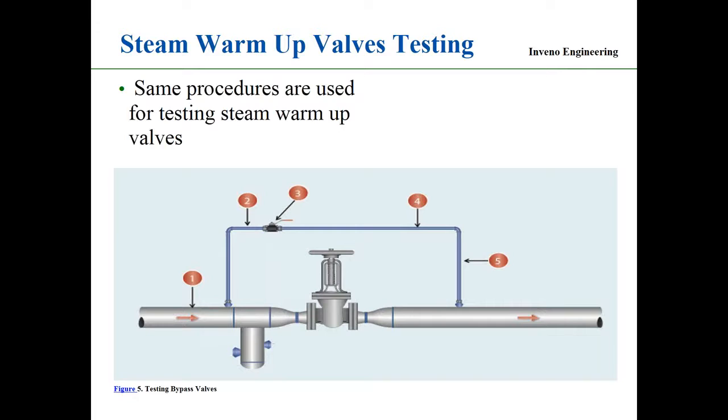So ultrasonic sound is very directional. By taking these points and seeing the increase at the discharge side of the valve, that tells us it's leaking. All ultrasonic levels should be pretty close. Nothing's going to be perfect. They're not going to be 25, 25, 25. Life's not perfect, okay? So as you see, the increase is there, ultrasonic sound is being generated. And that's a quite common process that we use on warm-up valves all the time because we want to make sure that they are in the seated position. Specifically, if we go through a shutdown at the end of the year, we want to make sure we know all the valves that are leaking and get them corrected.